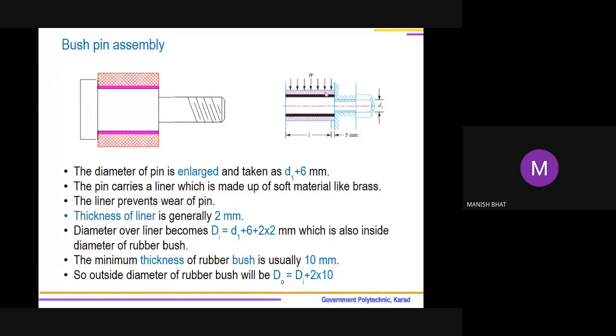So the bush is able to turn. As the bush is able to turn over the pin, in between pin and bush there is relative motion. Secondly, two different machine elements are there. So what mode of failure? It is bearing pressure. There are two localized compressive stresses.